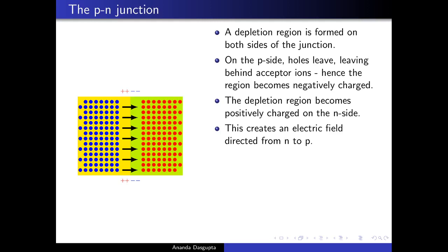So the electric field here, this internal electric field across a junction, plays a rather strange role. Instead of helping current to flow, it actually prevents or lowers the diffusion current. But suppose you have an electron here on the p side.